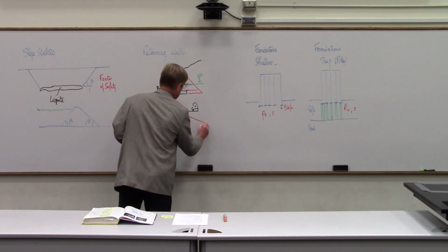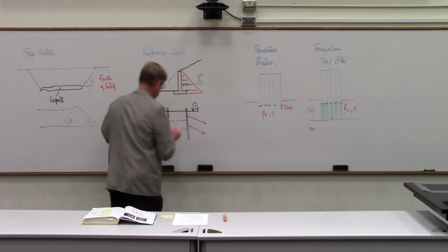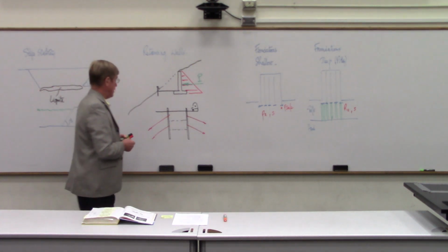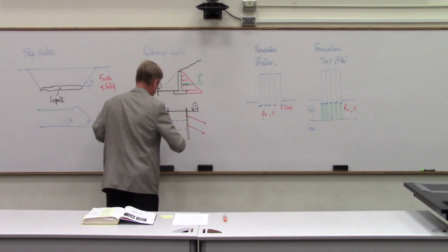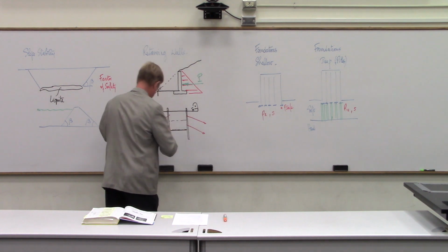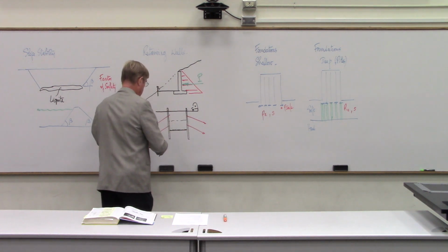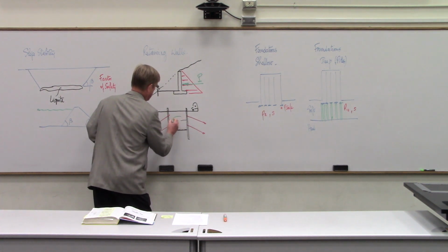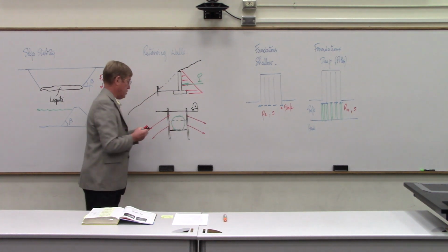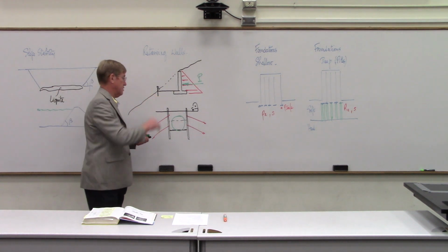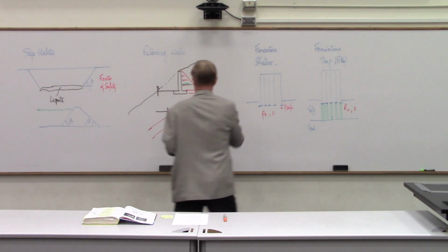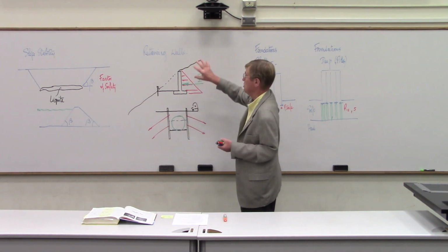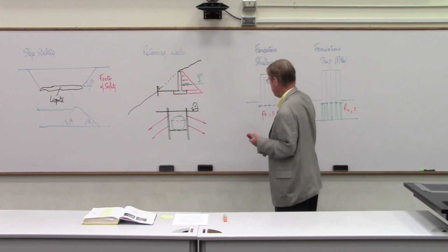So you take half the street, and then you put your sheet pile, and then you excavate between the sheet piles, and as you go down, you place some anchors in the ground. So you anchor the retaining wall to be sure that it's going to be able to hold, and then you can come back in here and put maybe a subway line or whatever you're trying to place on the ground, and then you backfill, and so these are top-down structures. This is a bottom-up structure. This is a top-down structure, both retaining structures.